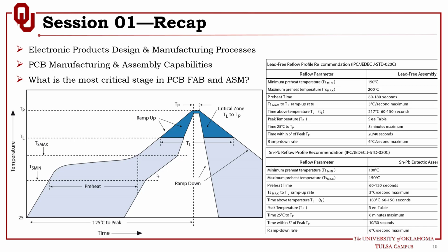So all that you need to do when programming your reflow profiles is to go to the suggested profiles published by the producer of your solder paste and by the manufacturer of the components you have on board. That concludes the recap for the last session, and we can move forward.